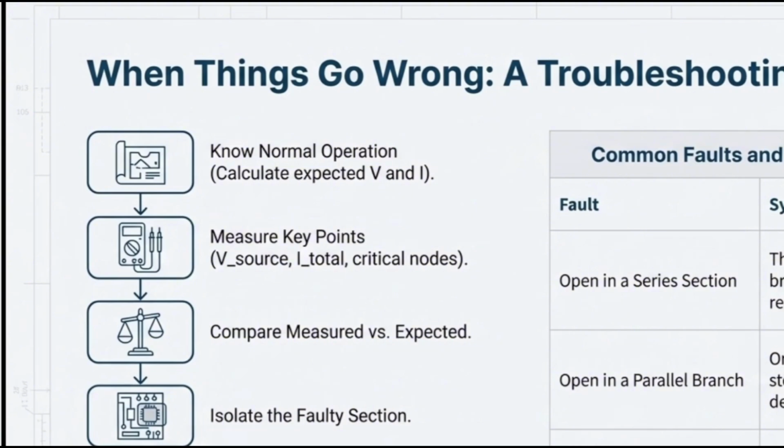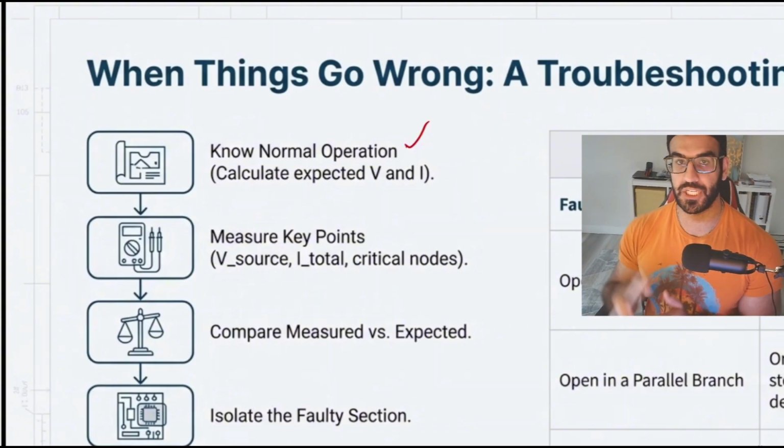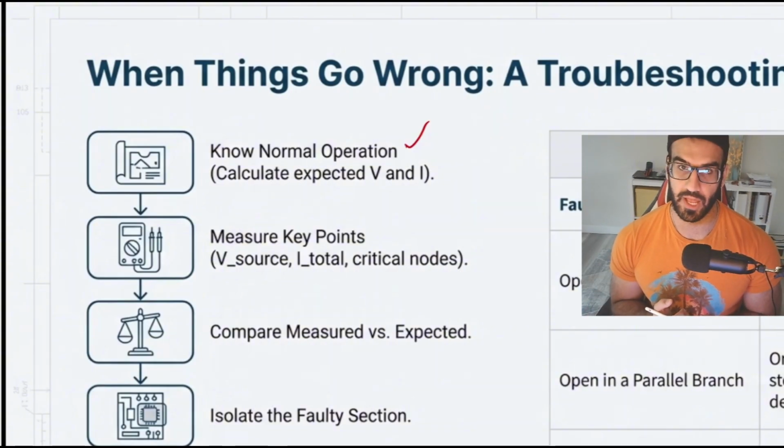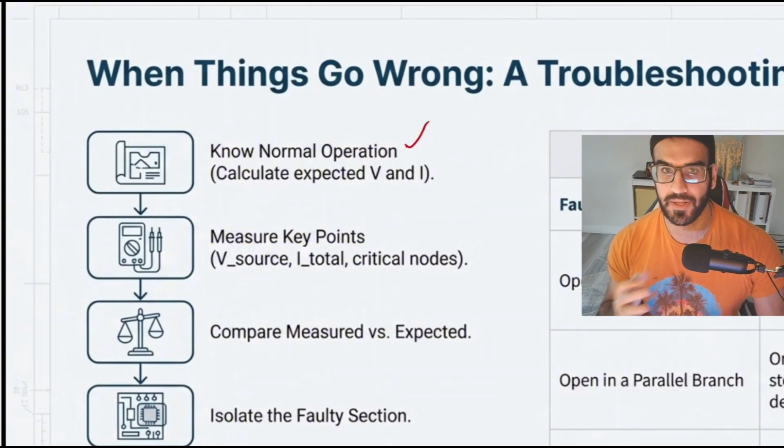So the very important thing is that in normal operation, you can calculate the expected V and I. It means that at this point we are going to compare our calculation with what we have in real life. That's why it is so important to have the calculation, to have an idea of what you expect from the circuit, and then try to compare those. And if anything happens, you can troubleshoot it